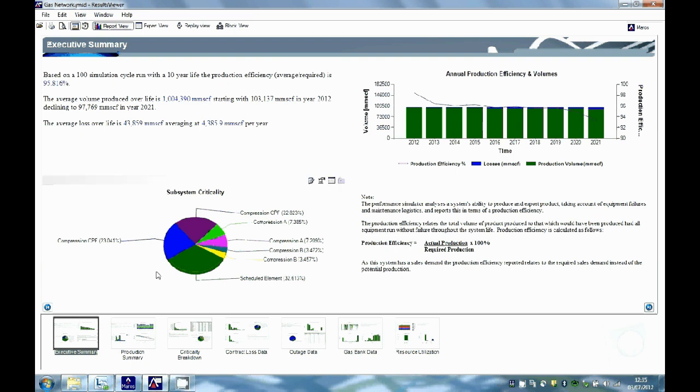We can now ascertain which systems are giving more losses, such as we could hire more personnel in order to reduce the time taken by the annual planned shutdown. We could check what is the best day to run the annual shutdown. Perhaps we are running it in high demand season, which could lead to more losses. Or we could increase the reliability of the CPF station by buying more reliable compressors, or by adding a spare compressor. And this exercise can be done until the new implementations are no longer worth the investment.